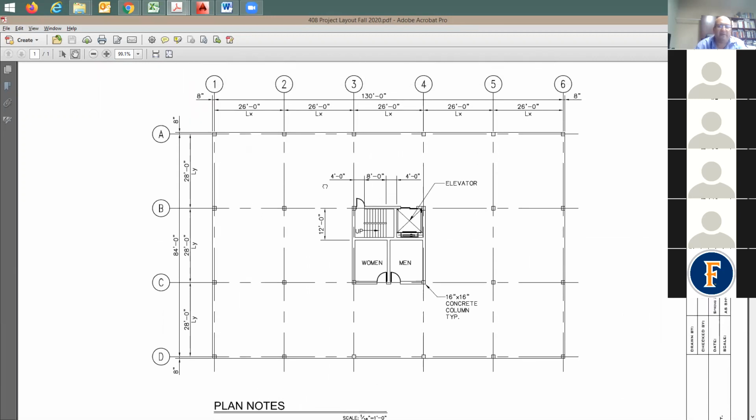It's okay if you'd like to make it 18 by 18, as a structural designer. They give me here what I call grid lines. This center line is what I call grid lines. I have 2 sets of grid lines. Some run in the X direction or longitudinal direction, called A, B, C, D. Then you have 1, 2, 3 numerical running in this direction. The spacing here is standard, like 26 feet, same module. The total building length is maybe 130 and a fraction. Same thing for the width, 28 feet, typical. This is the standard.